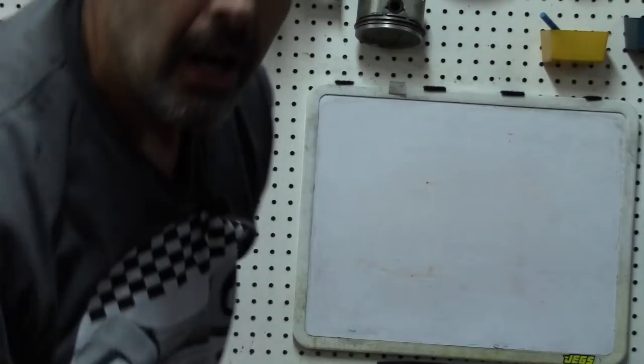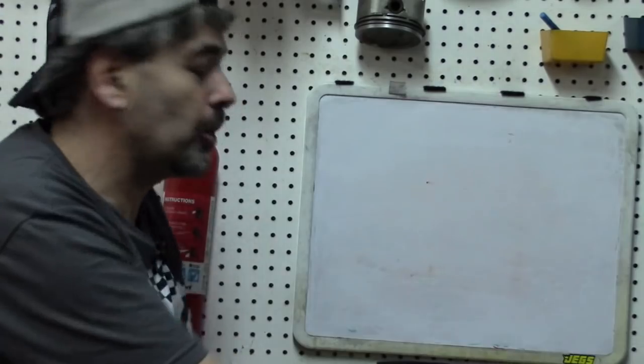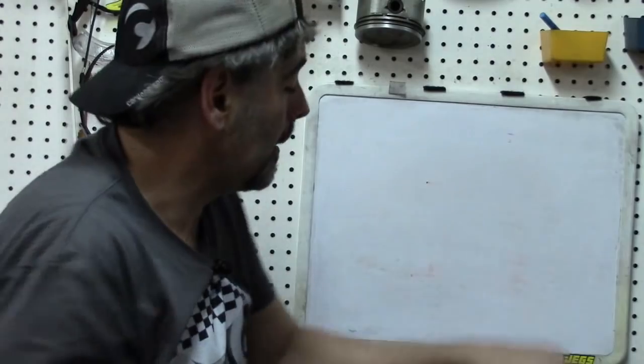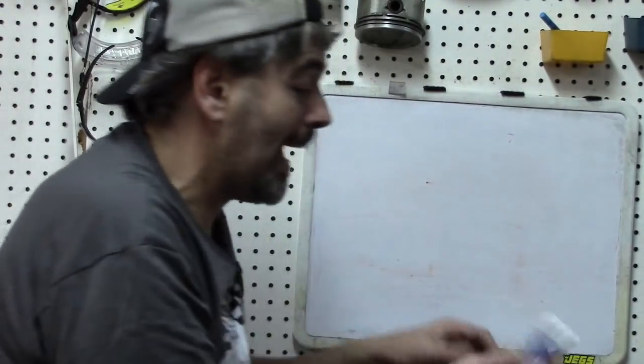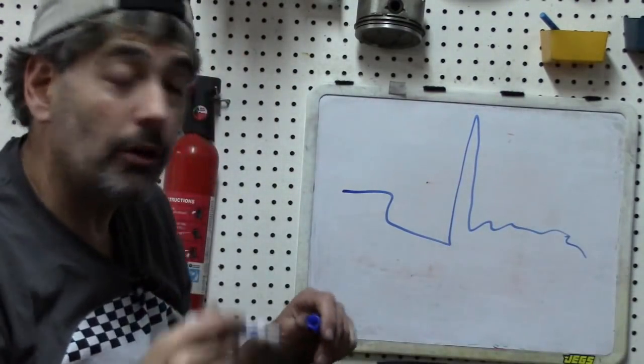Don't worry about it. Okay, I'm going to break for an emergency public service announcement, because it did occur to me that we shouldn't wait till another video. After this video you guys are going to be fully capable, with complete confidence, of going to your own car's ignition system, whether it's a 2, 3, or 4 wire system, and you are going to be able to map it out. But those of you with oscilloscopes, or even if you want to do it with a DVOM, you may be tempted to look for that spark voltage spike.